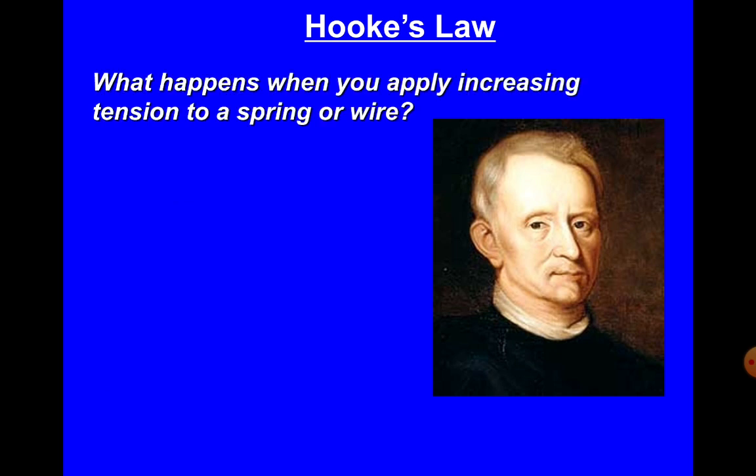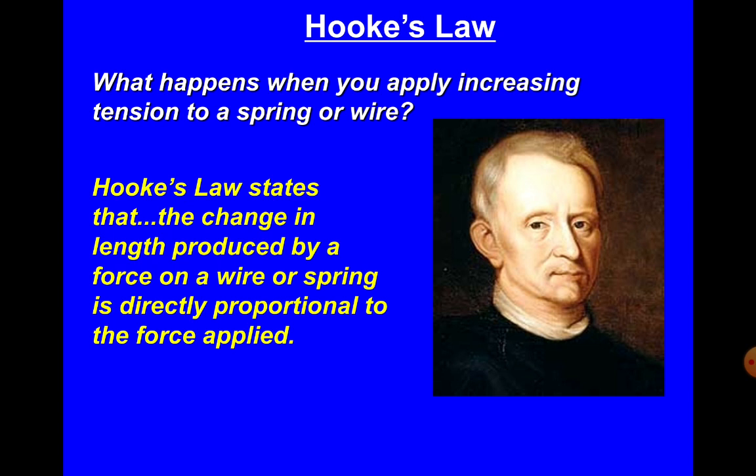Hooke's law. What did he see? He stated that the change in length produced by a force on a wire or spring is directly proportional to the force applied. When we are talking about directly proportional and you're making a graph, remember not to forget that directly proportional means that the graph starts at 0 and has a straight line up. In other words, in this experiment, when you double the load, the extension is doubled.